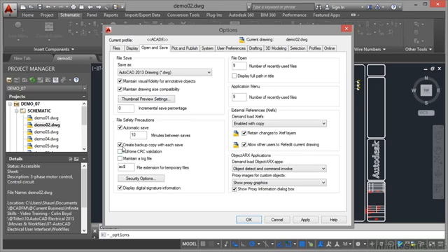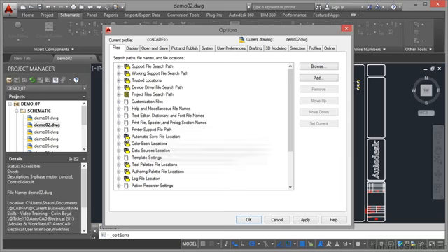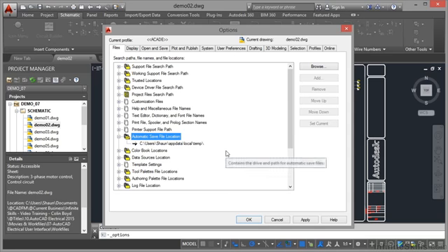Now, the other thing I always do is create what is called a backup copy with each save, a BAK file. Make sure that you do your autosave, and in your Files tab, you've got an automatic save file location. Mine just goes to a default temp folder on my laptop, purely for training purposes so that I know where they are. But you could specify something like a server drive so that if your local PC with AutoCAD Electrical crashes, you can go to another PC, log in, use AutoCAD Electrical on that, and find your drawings in the automatic save file location.